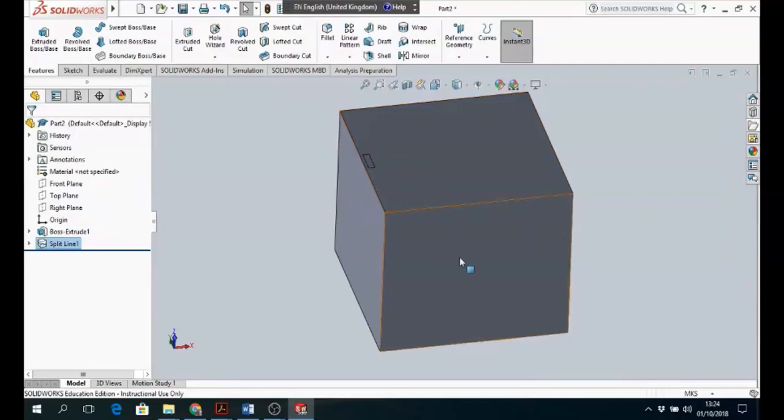So next up on this wall beside it, we want to put both a window and an outlet down here. So that'll be two rectangles, each of which are about 1.5 by 1.5 high by 1 meter wide. So if we select our plane here, I'm going to do it on this plane and project it onto this face here.